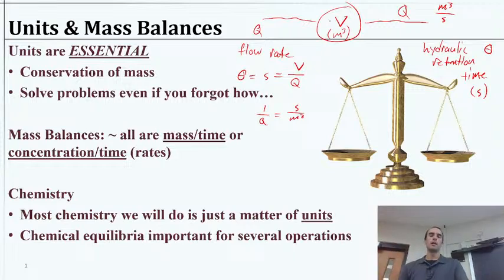That means in our example up here, at what rate, in terms of, let's say, kilograms of water per time, is it filling? At what rate is the chlorine decaying? That's milligrams of chlorine per time. So it's going to be mass per time for our rate equations there.